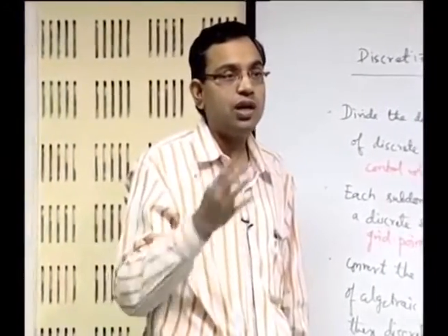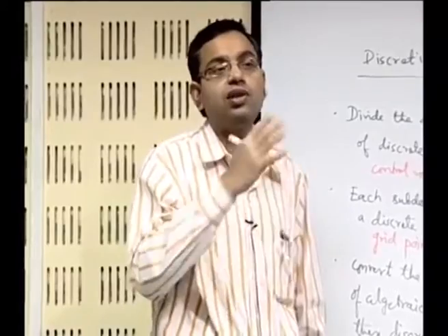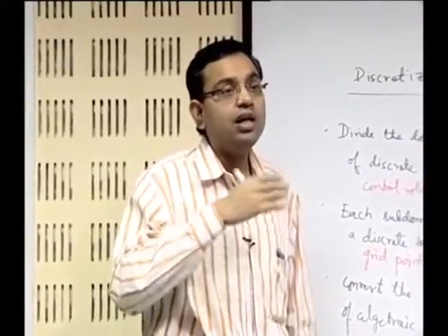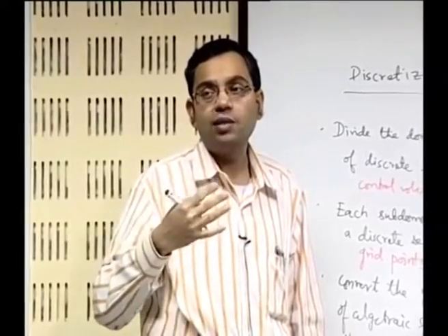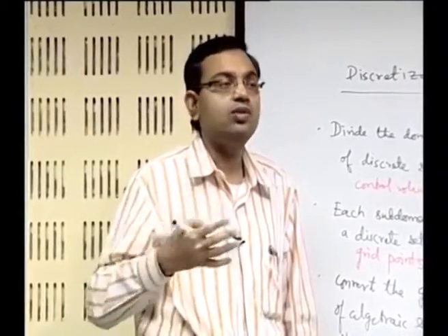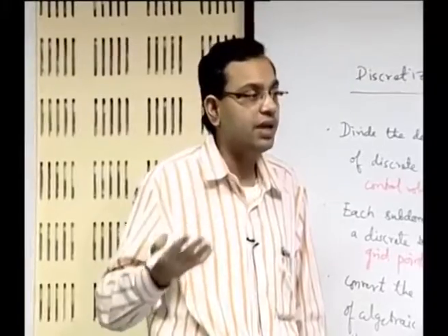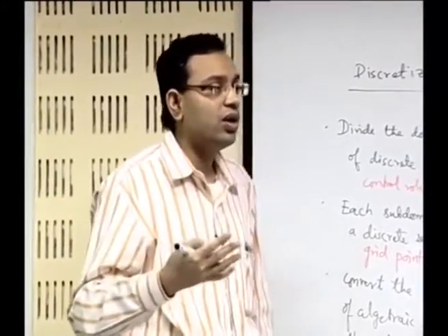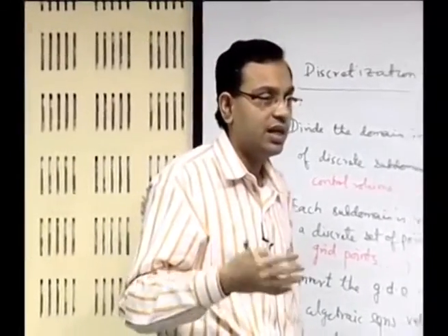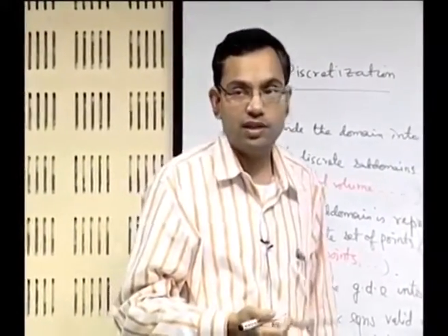Your objective is to convert the ordinary differential equation or partial differential equation, whatever, into a system of algebraic equations, and there you apply the particular method that you are intending. It could be finite element, finite difference or finite volume. How we can do that? That is where the heart and soul of computational fluid dynamics lies, and that we will take up in our subsequent lectures.